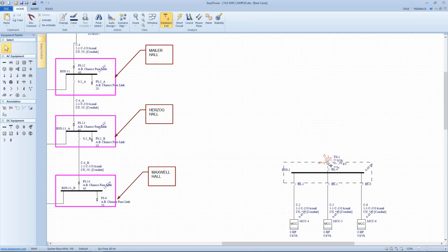bring down, each building has the step-down transformer connected to it. And then I need to connect up my cable to the high voltage distribution point, which is going to be somewhere up on the top of the building. So bring down the connection for the 13.8, and you can see that it's understanding what I'm trying to do as we connect the OneLine.